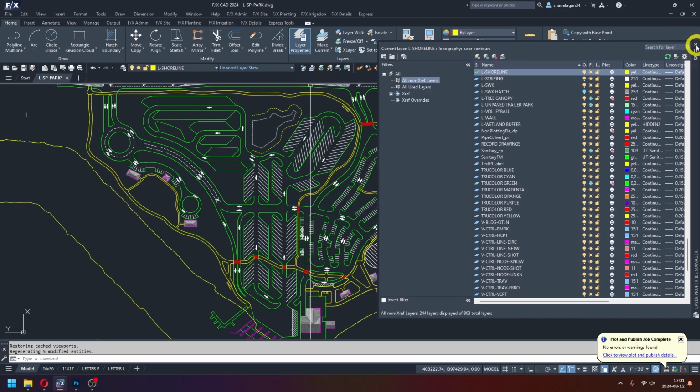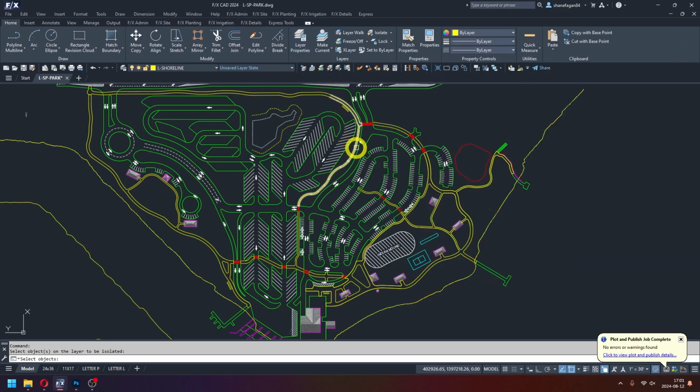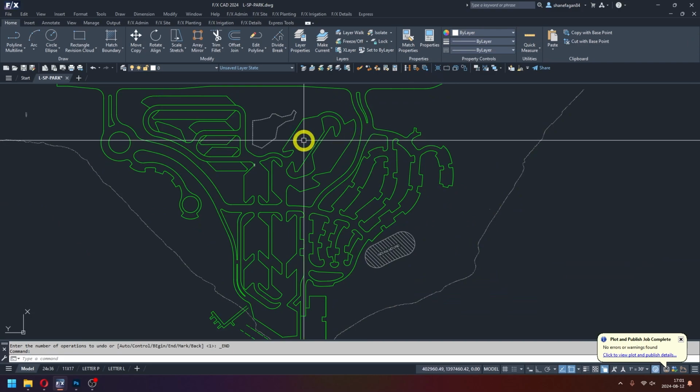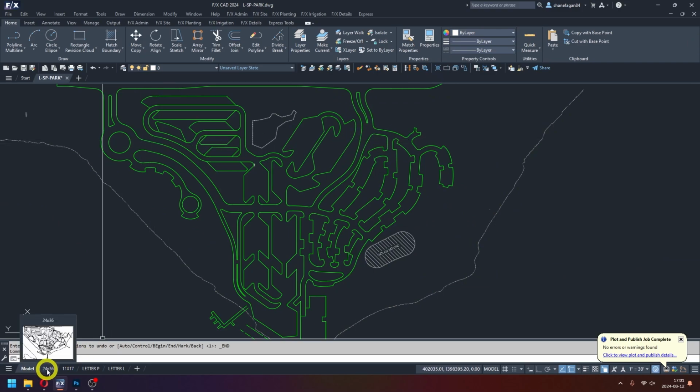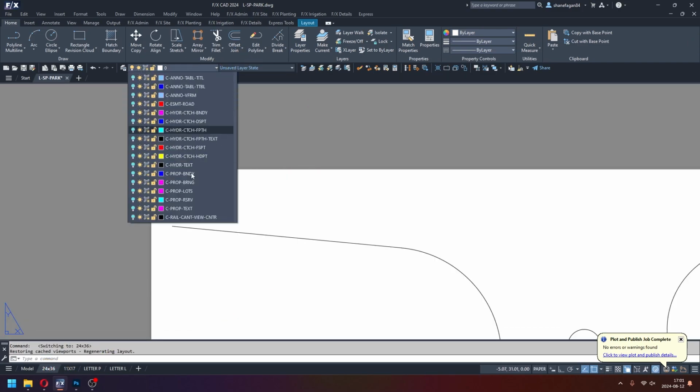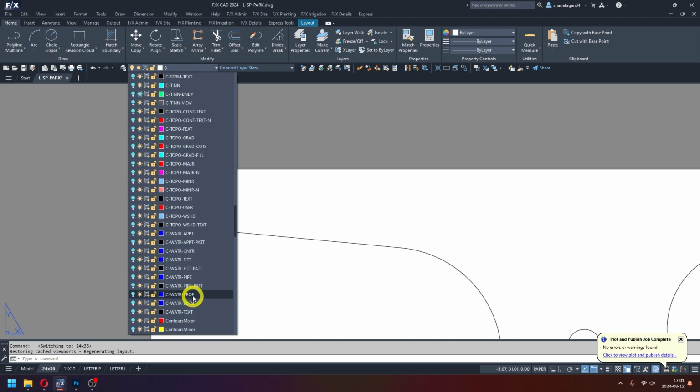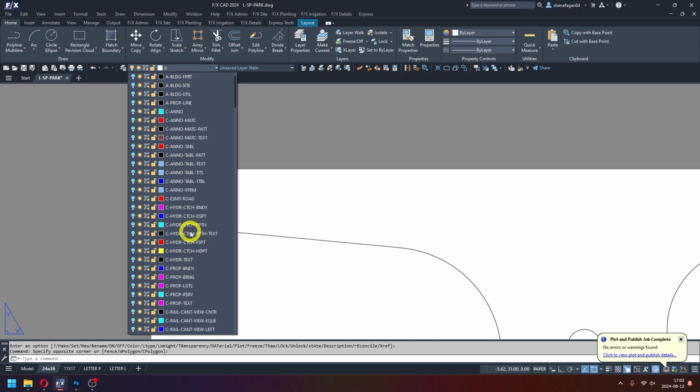Let's close this. Layer ISO, edge of pavement. We'll go back to here. Make sure our Z border is on. It was on drain pipe, I believe. So let's make sure we shift it over before we change it.